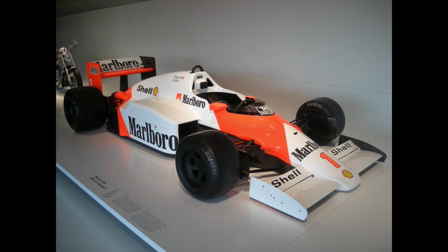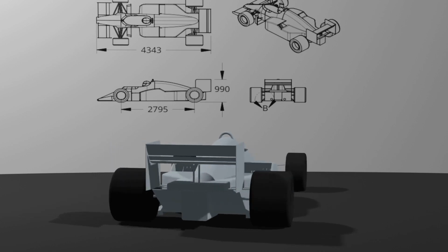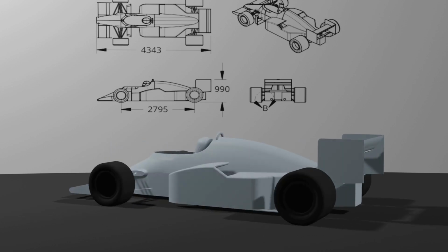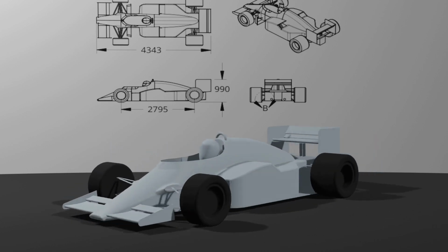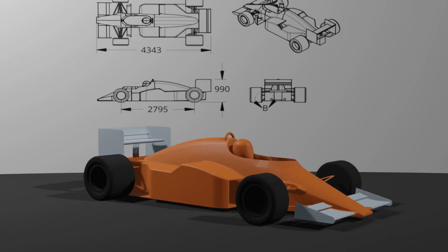Other changes that won't be addressed here were the changes to the mirror, and the radiator exits seem to be a little bit further back. There was a change to where the turbo inlet was located, but this seems to be more of a packaging rather than an aero thing. This experiment ran 4 simulations running 4 different model configurations. The changes included end plates, diffuser tabs, vertical deflectors, and windshield.